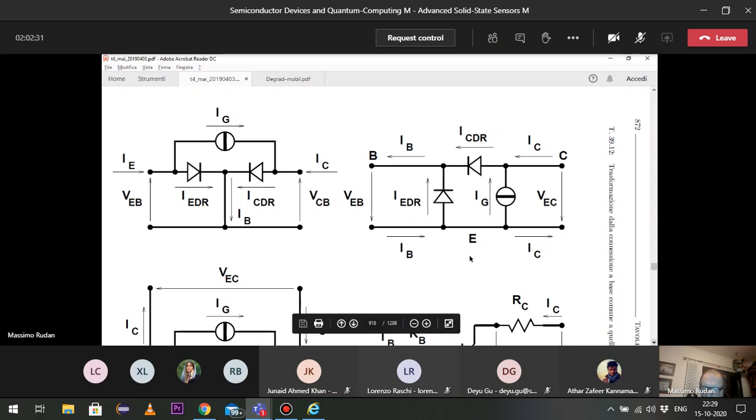Okay, there is only one thing left, that this analysis refers to a completely one-dimensional device. You remember, which is rather unrealistic because the base current flows laterally with respect to the device. So this is fixed qualitatively by adding a series resistance to the base, okay?